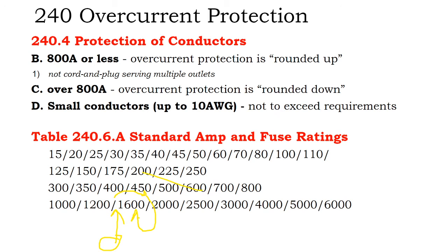And so what that means is on these larger systems, if I'm ground faulting the system capacity into my ground, and my ground is sized for a 1400 amp system, my conductors are sized for more than that.